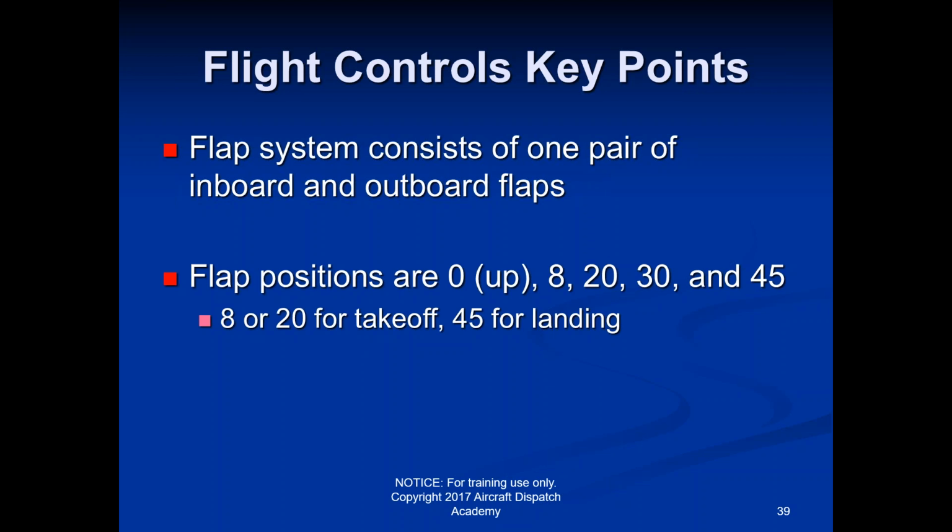They probably only use it for maybe 30 or 40 seconds. As you start to descend and get close to the airport, you'll go flaps 20, they'll leave it there for a minute or two, then flaps 30, and leave it there for a minute or two, and then eventually all the way down. I'm sure you've seen it: you see it go down, a few minutes later some more, and then ultimately all the way. And when they do go down all the way, it's usually a combination of several things.